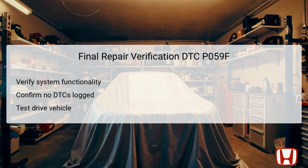After completing the troubleshooting steps and performing necessary repairs, you should verify the entire system's functionality. This involves rechecking the shutter grille assembly and its corresponding actuator to ensure both are operating correctly. Utilize the Honda Diagnostic System, HDS, to confirm that no additional fault codes are logged in the system after your repairs.